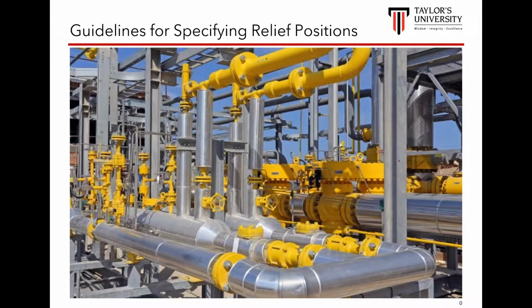So the procedure for specifying the locations of relief systems requires the review of every unit operation in the process and of every process operating step. So the SD engineers, we have to anticipate the potential problems that may result in increased pressure. You can see from these pictures, you have all the small vessels, you have the pipes and all that. So we have to look at it one by one. And pressure relief devices are installed at every point identified as potentially hazardous, that is, at points where upset conditions create pressures that may exceed the MAWP.